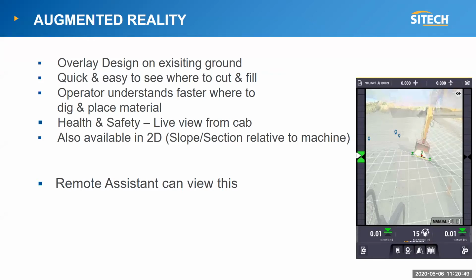Okay. The questions come in: real-time mapping, is it done using GPS location and measurement based on reporting the control box, or is it off the ground? And I think it is both the track point and also the bottom of the blade, isn't it? It's the bottom of the blade, or the bottom of the tracks, or the tip of the blade, depending on what option the operator selected to record. Indeed. And then beyond that, can that information then be exported on a CSV or similar file format to give a live comparison model to the surface in the field? So we export it, or we create tag files, which can then be uploaded to VisionLink.